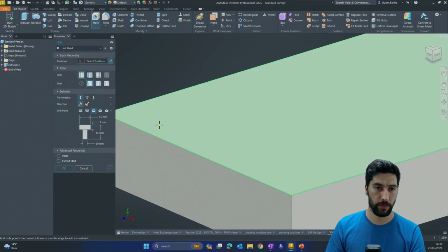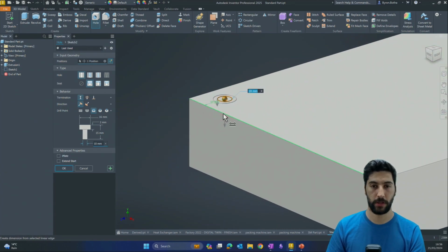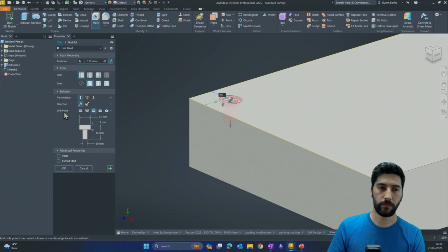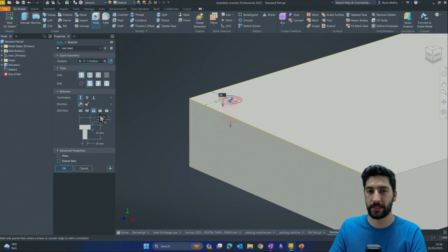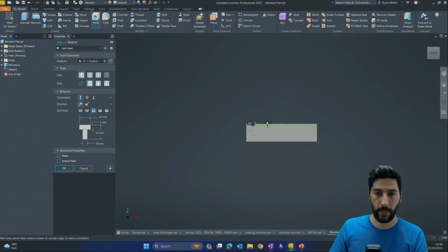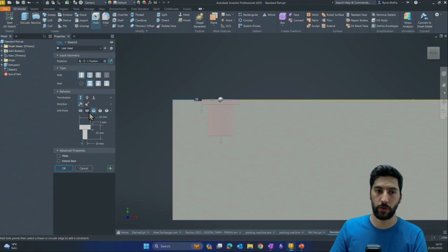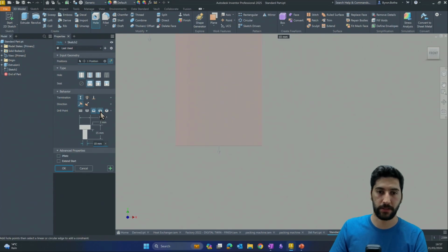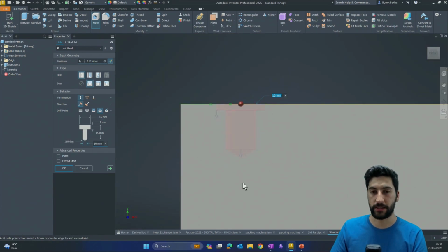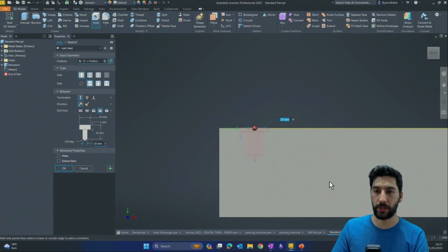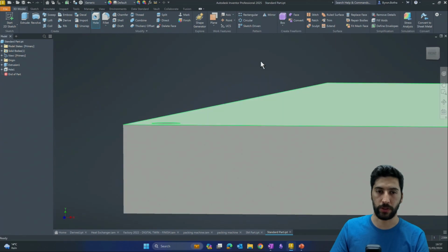And then I'm just going to place in a hole in the top left of this base here. So 20 mils from that edge, 20 mils from that edge. And you should notice that we have these new drill points available to us within Inventor 2025. And these just coincide with the latest ISO standards. Rather than just having flat or pointed, we have these W, V, and Y standards. You can see the W is flat, or I could go for the V that has that drill point. And again, those are just taken from the latest ISO standards. Press OK there.